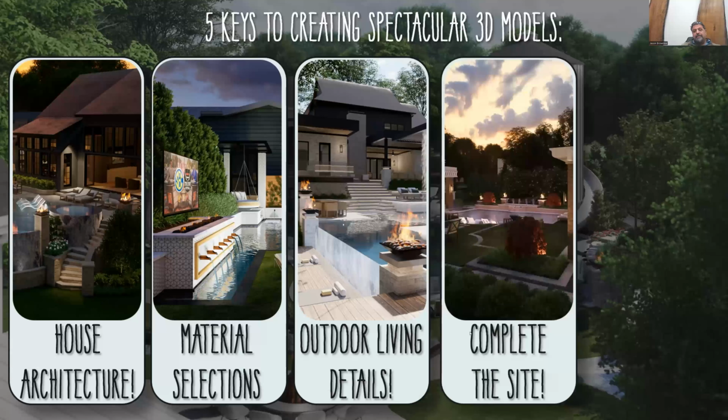And the other thing I see, especially in Structure Studios, is to complete the site. Don't just put it on a sea of green, with your house and your pool and no neighbors. When I was in Structure all the time, I would do all the neighbors around me. I would always want to hide the horizon line, so you put the trees in the background. You don't ever want to see where it falls off the face of the earth and disappears. Give it context, complete the site, have the elevations come in.